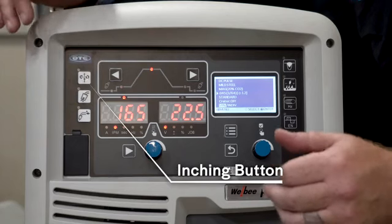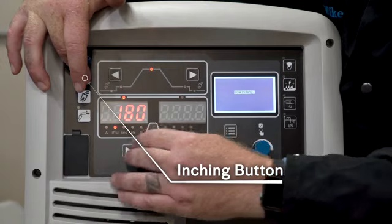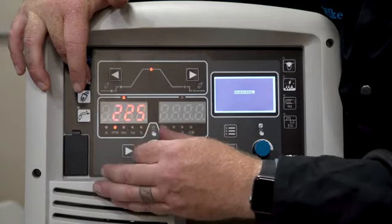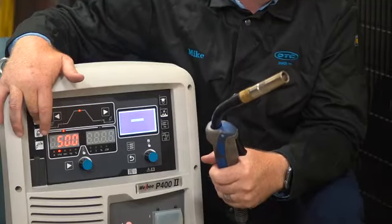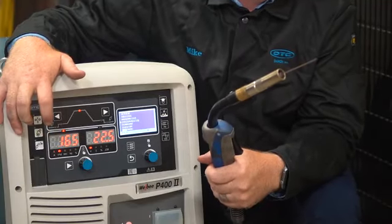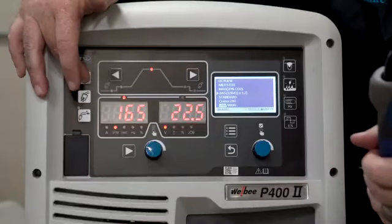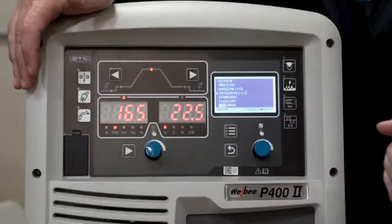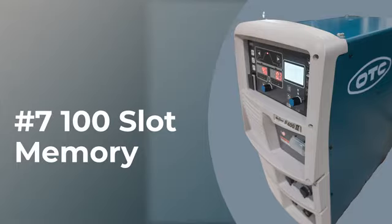On the Welbee II, we have our inching button. When I push the inching button, I have the ability to then increase the wire feed speed to allow for faster feeding of the wire through the gun. You'll notice when I let go of the inching button, my wire feed speed settings are exactly what they were before I changed the wire feed speed settings.